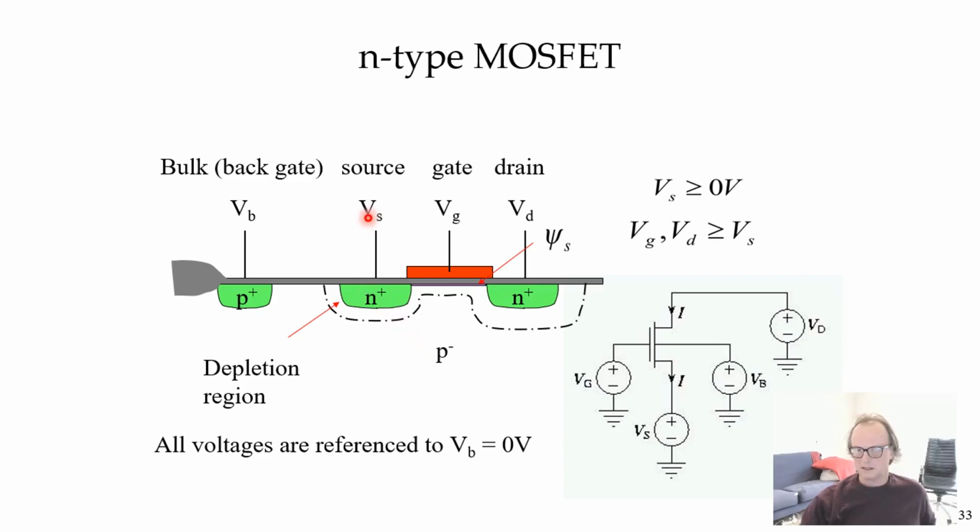And the transistor source and drain N regions are surrounded by a depletion region. Just as you saw last time between a P-N junction, there's always a depletion region. So this is N plus here. This is P minus, so these are neutral regions here. But around this, there's actually this PN depletion region. We only show it kind of as one side here. And actually in the channel, there's also a depletion region.